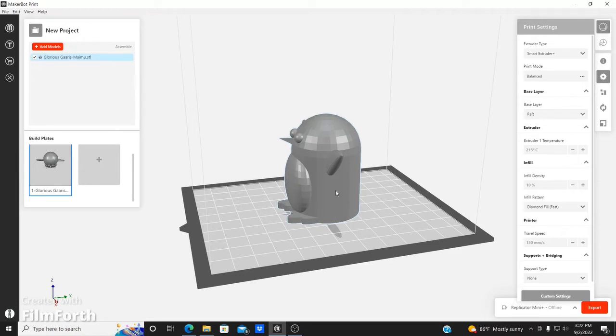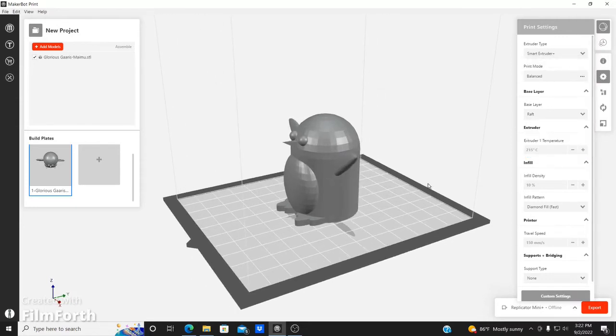It'll become a failure, because once it starts warping up, the rest of it will be affected. And once it continues printing above here, if it gets stuck, this guy will come off the build plate, and it'll just drag along here. So that will be a complete failure. So you have to prevent that one. So you have rafts or the brims or padded base. Those two are the ones that you can actually use. I'll show you that one on the next simulation, how you find that.